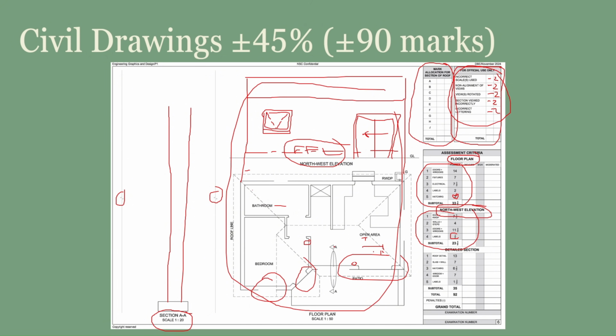If you look at the sectional view AA, you can see that it looks in this direction. The arrows are pointing in that direction. So you stand here and you look in that direction. So that is what you need to draw. So the outside is on your left and the inside will be on your right.